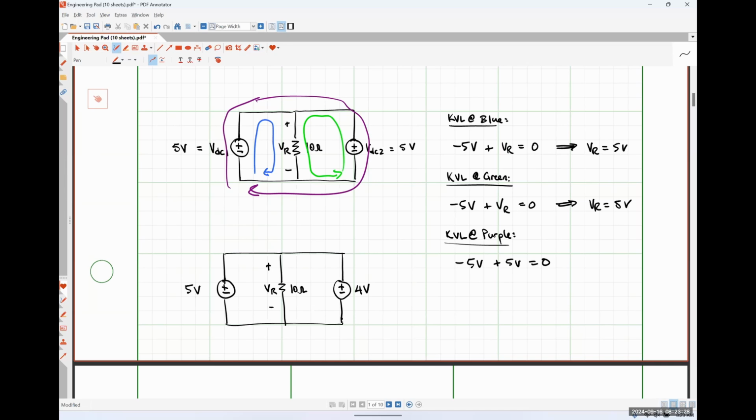Okay. For those of you who have ever had to change a battery or something like that in a car, or try to jump off a car, this is one of the reasons why you have to be super duper careful to make sure that everything is connected correctly and that you're using appropriately sized jumper cables, because if you don't, the jumper cables literally can't handle the amount of current that's causing the energy in one battery to flow into the other one to jump it off. And that's why you see all kinds of sparks. And every now and then you might see a fire if people aren't paying enough attention.